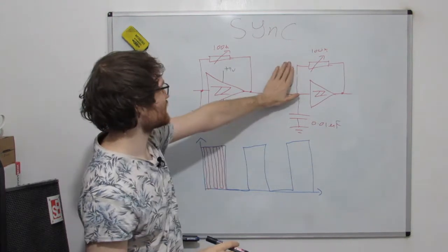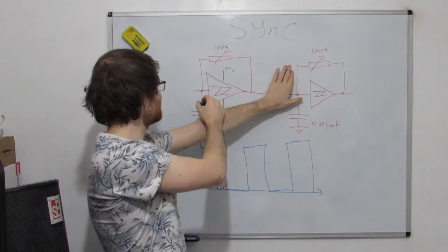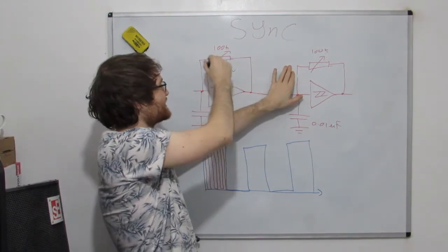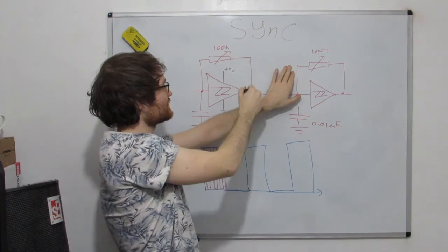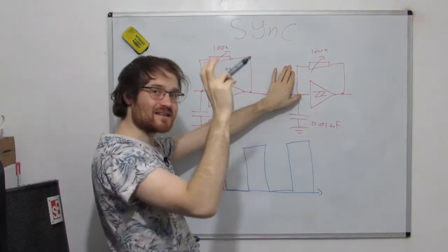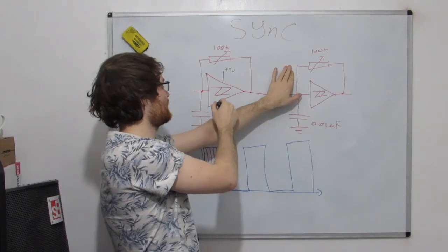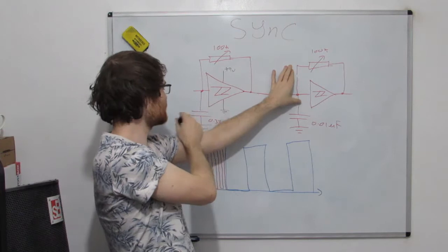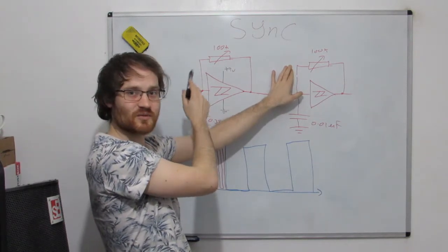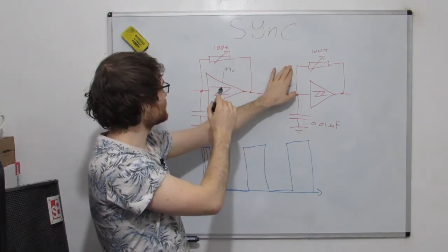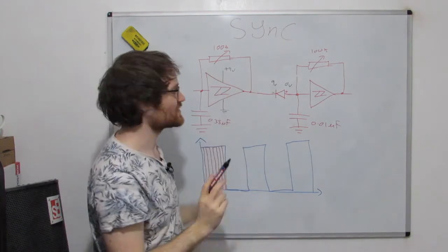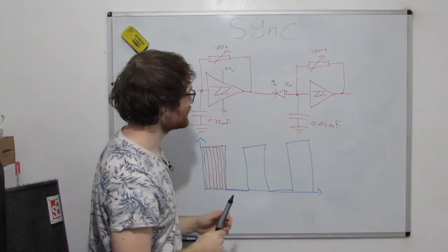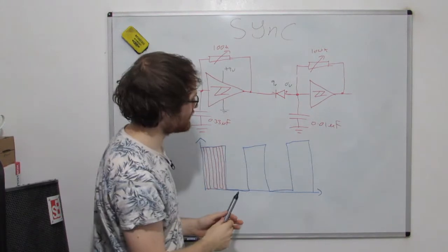So before, when we had this short-circuited, this capacitor would discharge through this resistor and into the output of the chip and down to ground, because this is the low potential. This was at around 6.66 whatever volts, but that's not what's going to happen this time. Well, that is what's going to happen, but what else is going to happen is the same thing's going to happen over here, because